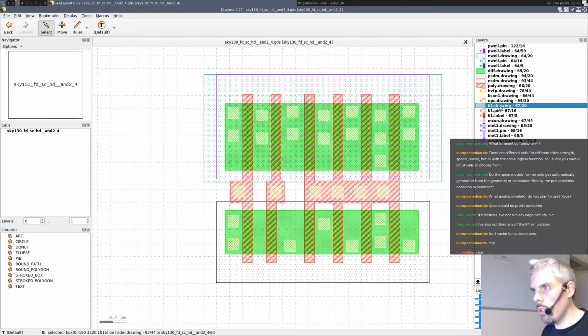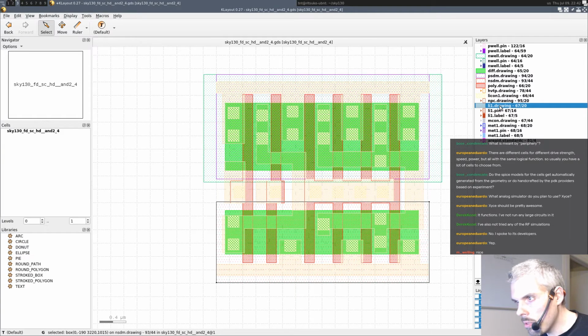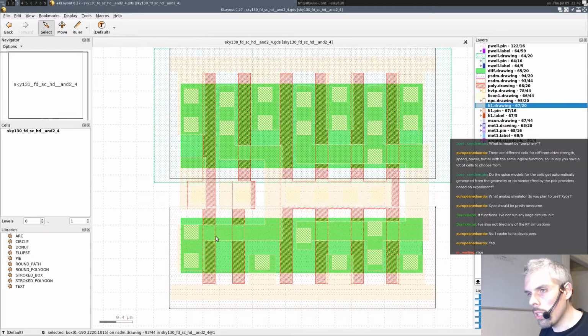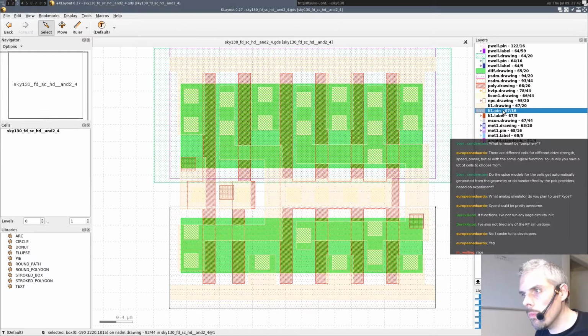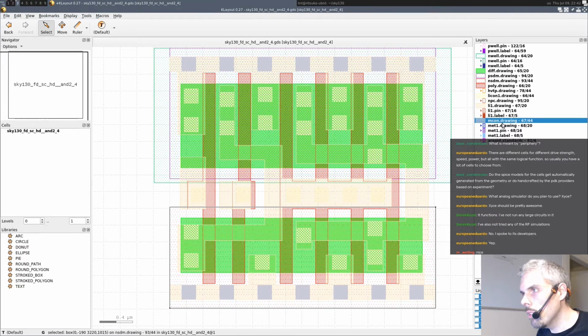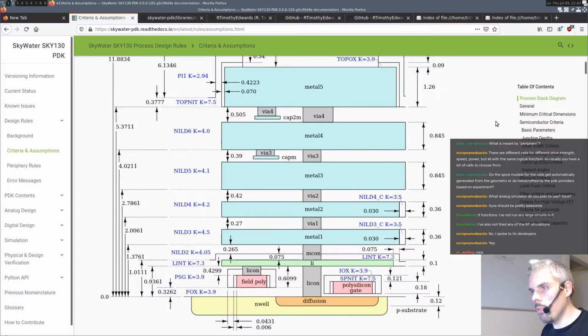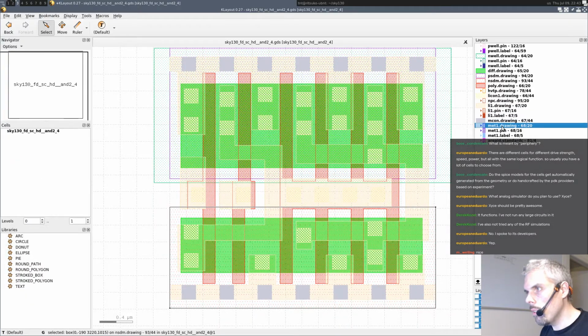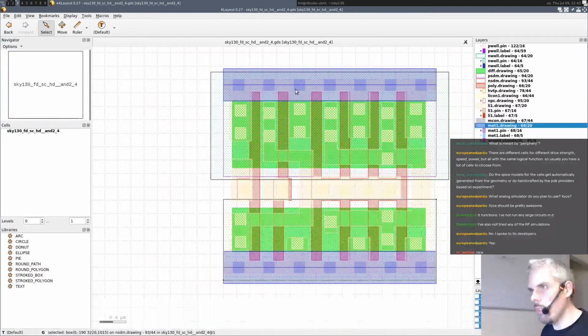And so here is the local interconnect, which is a terrible color, but okay. This particular cell doesn't have much in terms of metal. You just have the MCON, which is like this, which goes between the local interconnect and the metal one layer, and the actual rails, and these are just power rails, right? So that's the positive supply, and that's ground.